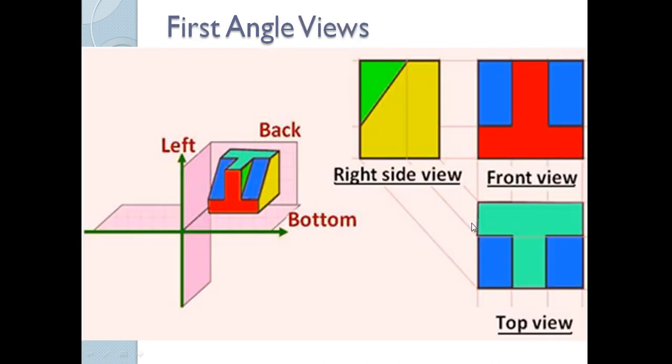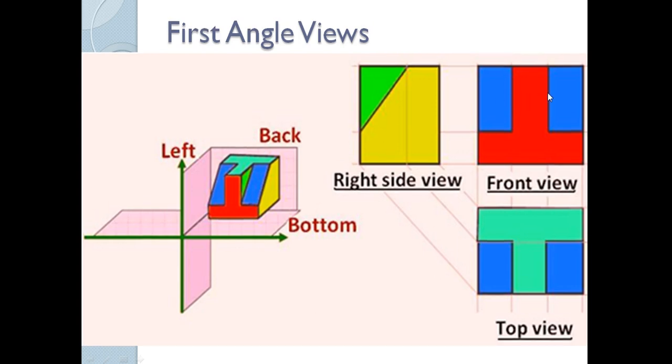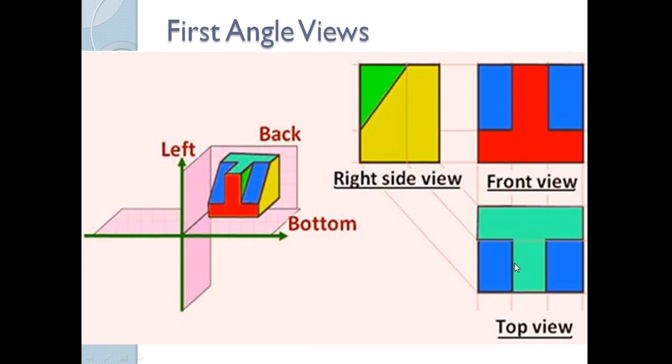So this is another example of a first angle projection. So you could see the front elevation with the red block there and the two blue sides, the right end view and the plan view or top view in this case. The lightly drawn lines are orthographic lines. They are used for construction. Normally the spaces between the views are evenly spaced and a 45-degree line transfers the corners or the same part of the object across to the next side.